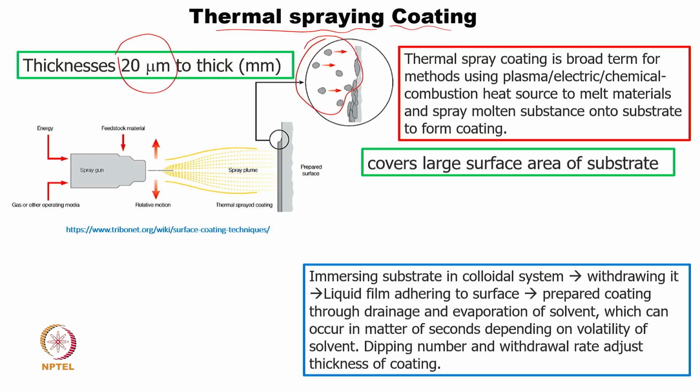However, a lot of the flexibility is that PVD and CVD we put in a chamber, a small chamber. So, we have a vacuum requirement, and in this situation there may be a need of some vacuum, but it may not be that much of a restriction. So, thermal spray coating can be done, and particularly if I am a designer, I can really design the coating and the environment in a way we want. However, because of these small particles, it will cause some sort of air pollution. So, we need to really collect them and keep them in a proper environment, and keep a check on that. However, as I say, the best thing is that it covers a large surface area of the substrate.